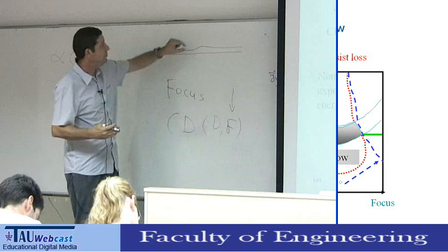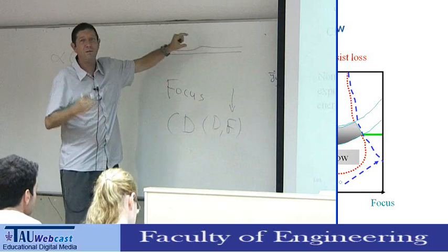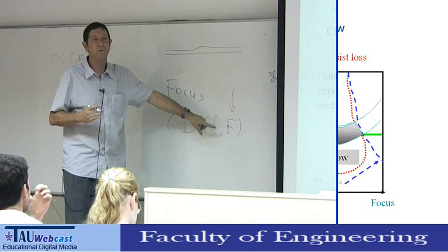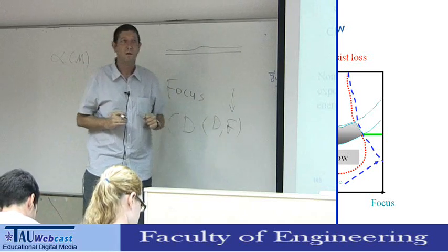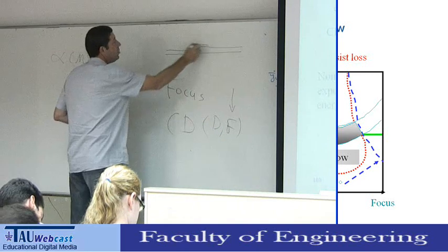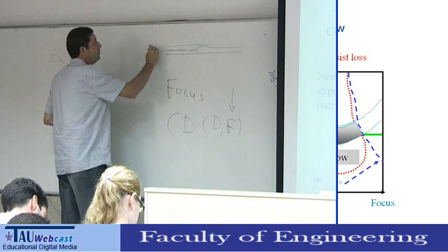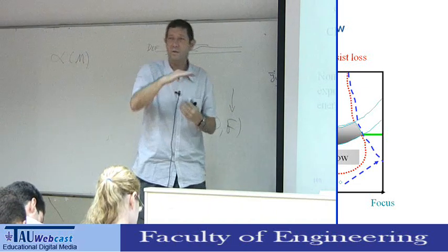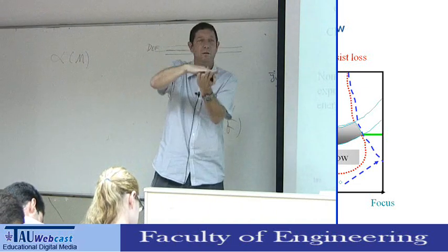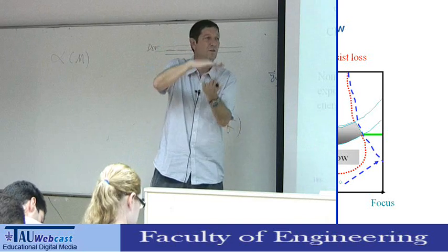So it's sometimes very difficult to avoid being out of focus. You have some defocus because of the shape of your wafer. How much you allow is called the depth of focus. You want to get the best resolution within a certain range of variations of the focus.